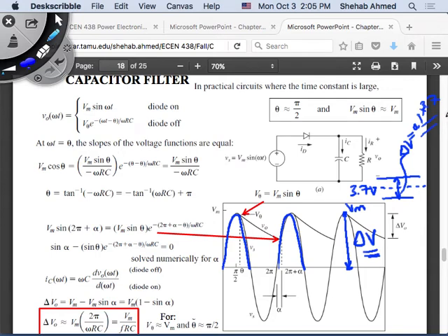You will have a ripple spec. Every power supply will have a ripple spec. It's part of what you have to do to build a power supply. You cannot just say, I want a 5-volt power supply, because somebody can give you something with an average value of 5 volts. That is nothing but this. It's a half-wave rectifier that has an average value of 5 volts. But this is not going to be something to power up your load. So you have to specify a ripple.